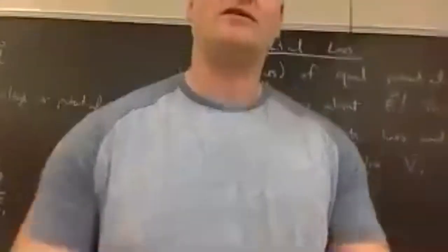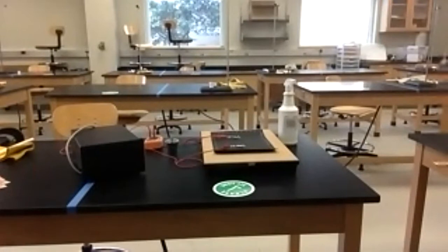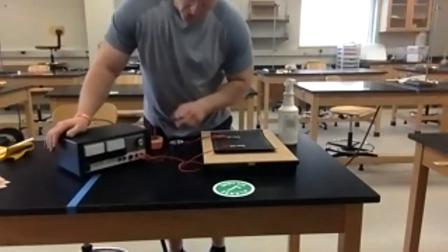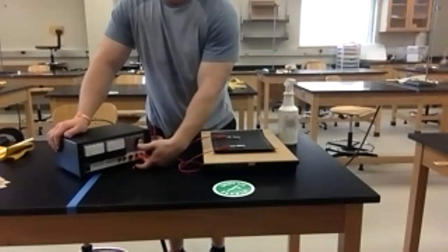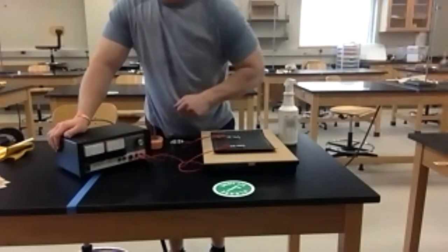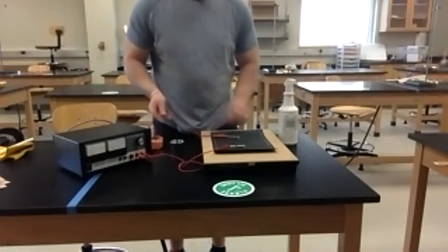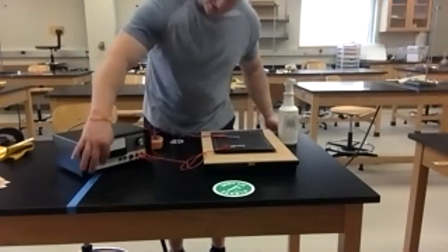So in this lab, we're going to be looking at that by playing with this system here. So this is our experimental setup for this week. So here we have a power source. Here we want to make sure this is connected to DC, not AC. DC means direct current. This side over here is AC. So basically from here, we're going to run one wire from the negative terminal to another wire to the positive terminal, and then go ahead and turn this thing on.